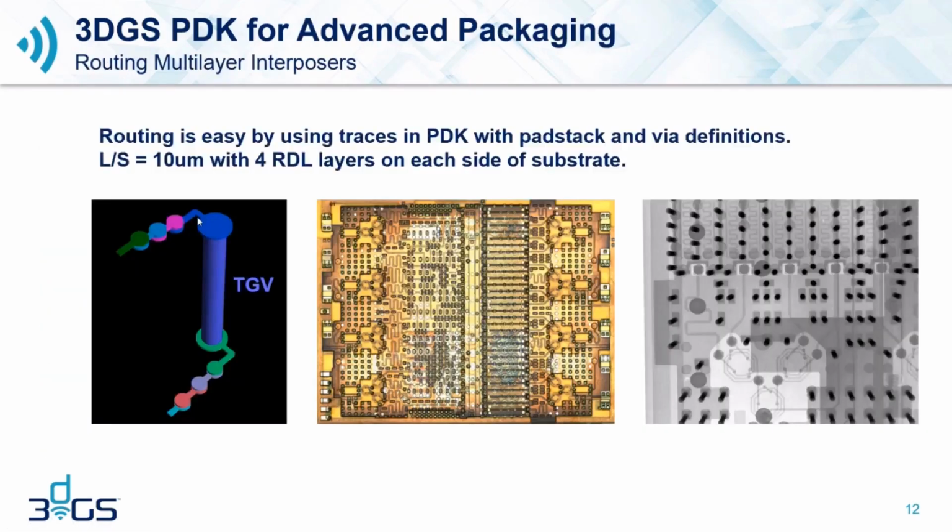The other main single layer glass design that we do for most customers are interposers. And here we're typically using more redistribution layers rather than passive components, although you can do both. We're able to do the routing inside ADS with substrate, pad stack, and via definitions.